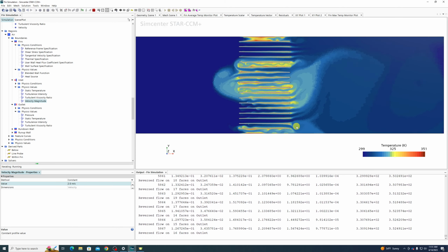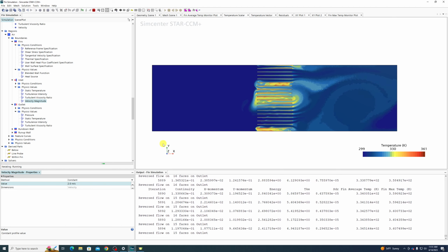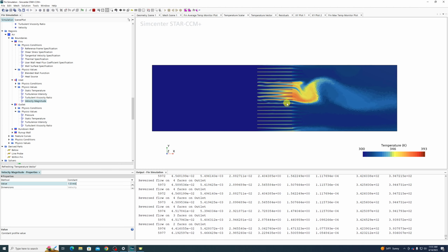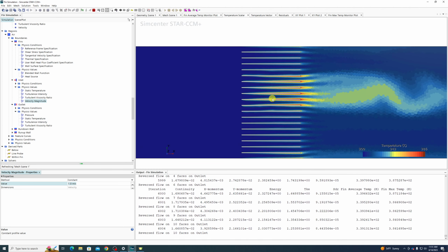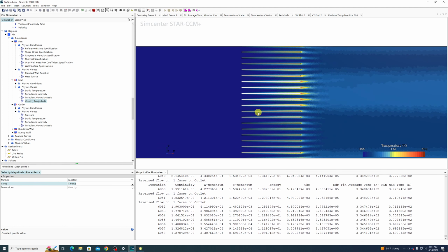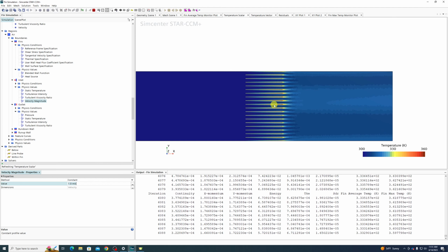Yeah, so down here at like 1 meter per second, natural convection is getting almost as powerful as the forced convection is, and is actually starting to be capable of driving flow backwards through these fins if there's a reason for it.